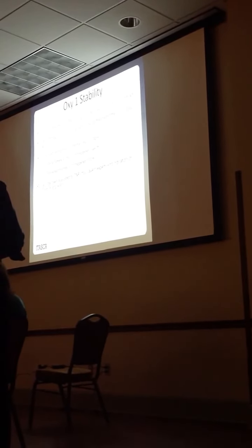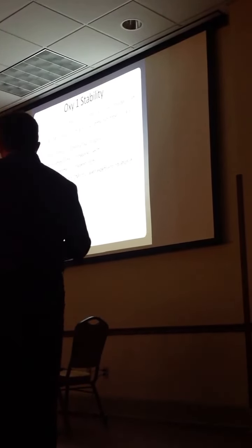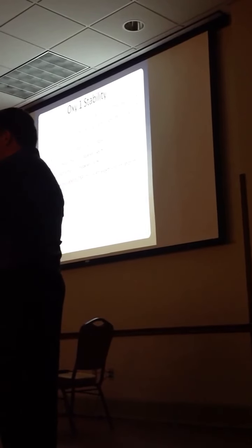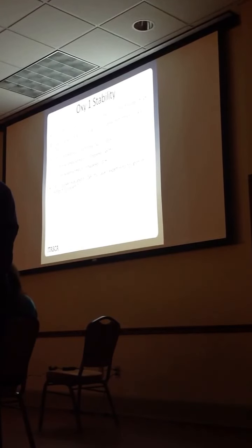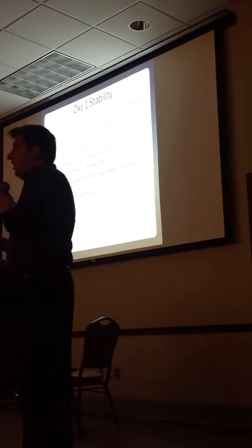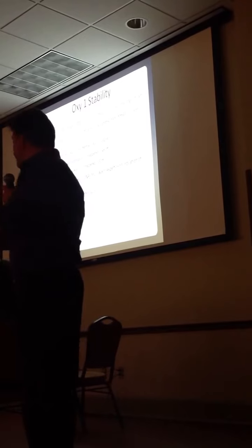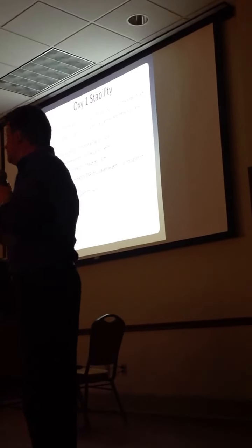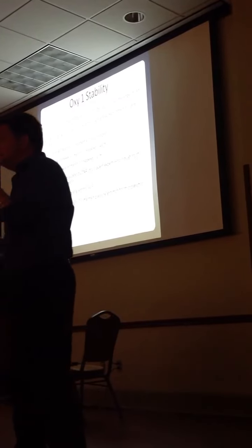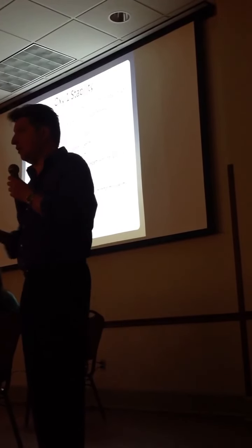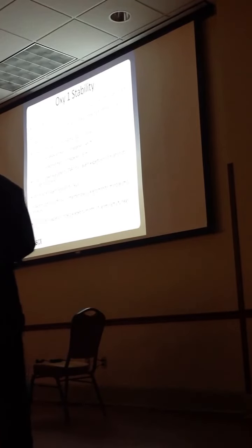The Oxy 1 cavern has also been looked at by 4 cavern experts that are contracted to DNR, and there is no indication of instability at present from any of the data. So there's no evidence whatsoever that the Oxy 1 cavern is unstable. Most of the seismic events that we're seeing, we now believe are around Oxy 3, so the continuing collapse of that cavern. The best thing to do with Oxy 1 is to maintain pressure in that cavern and to monitor the microseismic activity, to watch it, to observe what's going on. And that's what we're going to be doing.